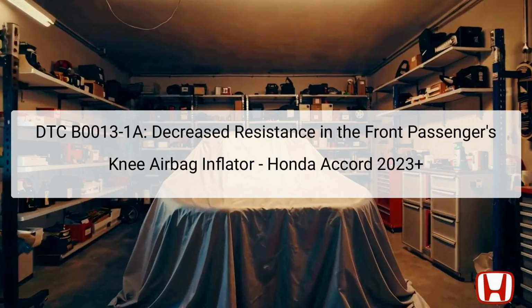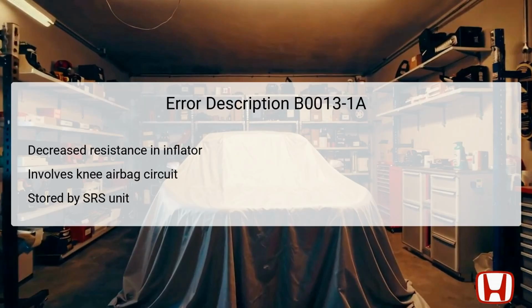This issue often arises when a voltage on the detection line in the supplemental restraint system (SRS) unit falls below a specified threshold, leading to the SRS unit detecting an abnormal condition and storing this DTC in memory for further diagnosis. Understanding the function and location of affected components, like the knee airbag and SRS unit, is vital for effective troubleshooting.